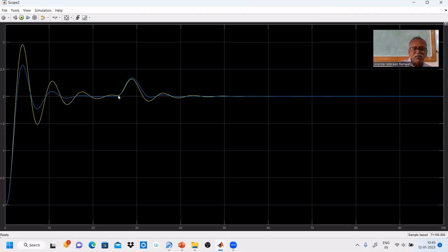At 25, we gave the disturbance. That's why this deviation occurs. Otherwise, it remains like this. The continuous cycling method has slight overshoot, but the undershoot is less. It settles around 50. Around 50, both settled. I did both in a single response. Here the set point is 0, so it is brought back to 0. Don't think that the regulatory response will always bring it to 0.